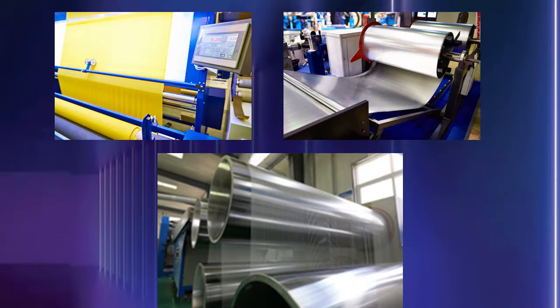Linescan cameras are ideal for continuous web inspection. Examples abound: glass, paper, fabric, plastic, and rolled steel. In these applications, the area to be inspected is relatively large, with typical widths of a meter or greater, and the material is moving fast and it doesn't stop. Because the width of these applications can be a meter or more, several Areascan cameras would be required to meet resolution requirements, and the high speed would necessitate costly lighting and camera scan configurations. A Linescan camera, on the other hand, delivers greater resolution across the web. The reduced scan time provides useful image data which is combined for downstream processing.